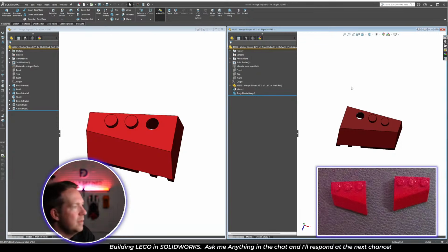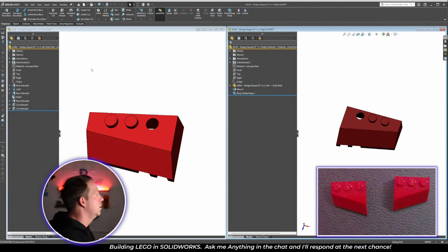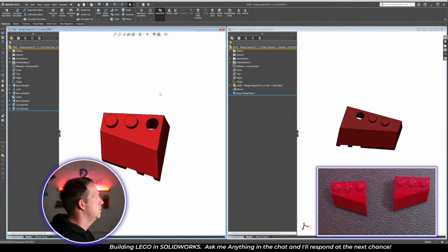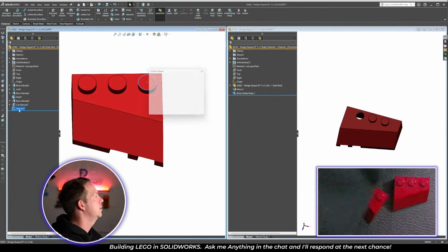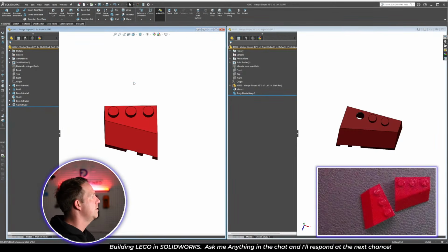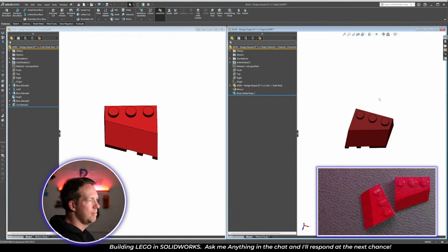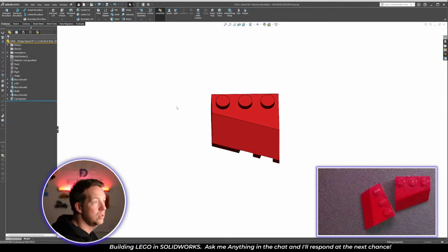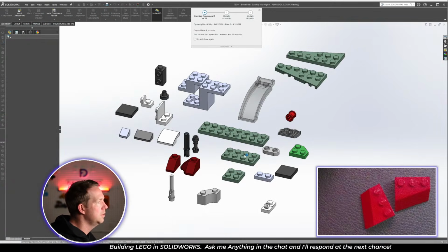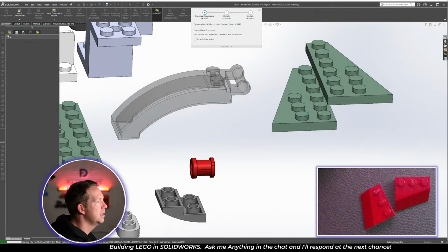Something I really enjoyed, that kind of system, top down. All right, so let's put these two features back. Let's remove those, close that sketch, save that file, click in here, that one updates, save that, and let's open my assembly, and we'll put them both in the assembly, and that's another 2 parts done very easily.